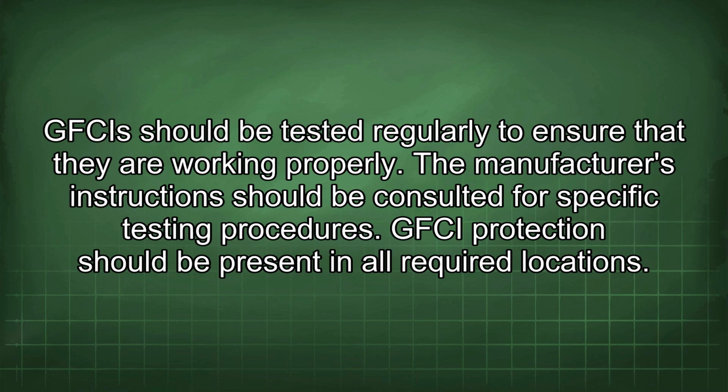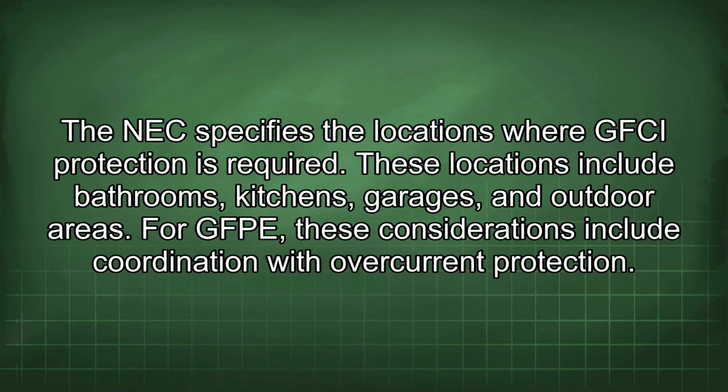GFCI protection should be present in all required locations. The NEC specifies the locations where GFCI protection is required. These locations include bathrooms, kitchens, garages, and outdoor areas. For GFPE, these considerations include coordination with overcurrent protection.